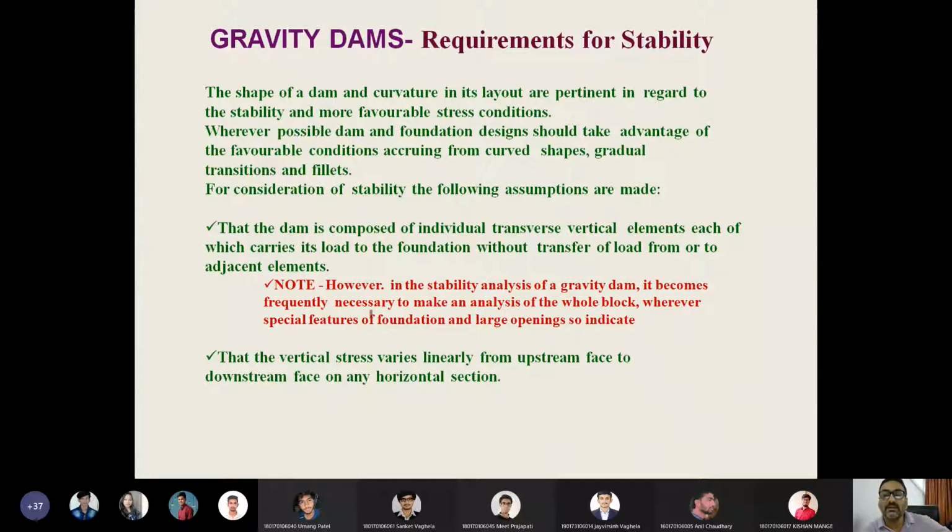I think you could understand the kind of geography we take, that I mentioned while showing you the contour map, that how we take it. If it is a small deep gorge, we could go for an arch dam like this, and otherwise if the foundation is like this, we go for a straight gravity kind of structure, gravity dam. So those kinds of mentions are here.